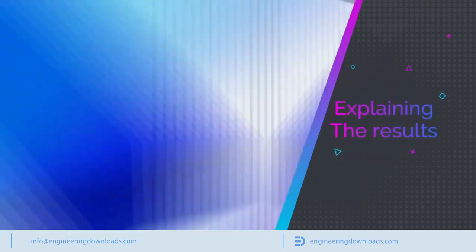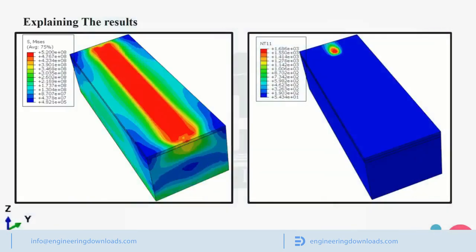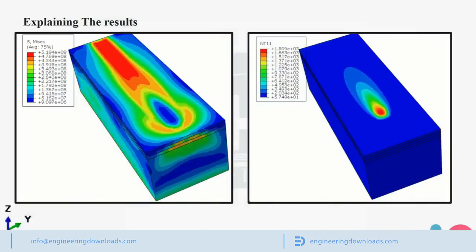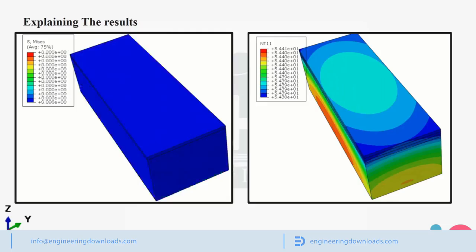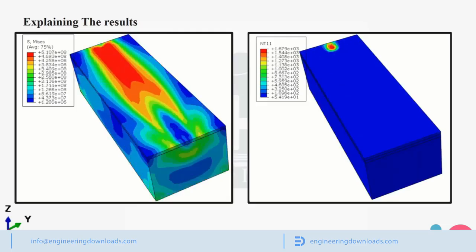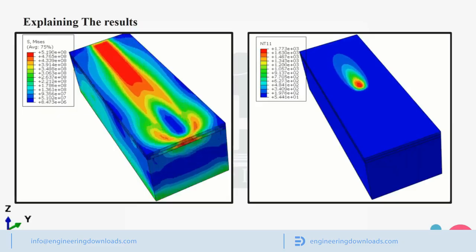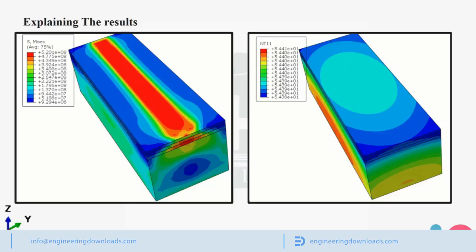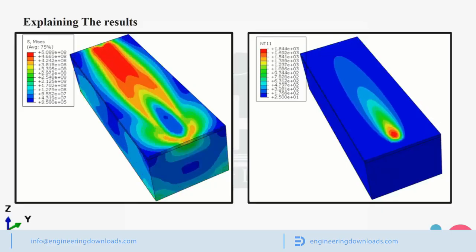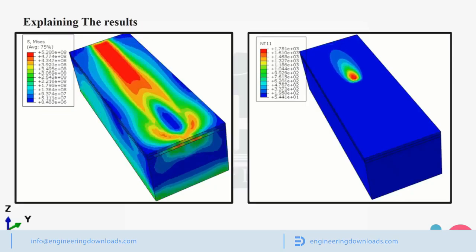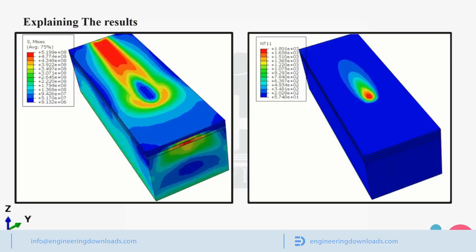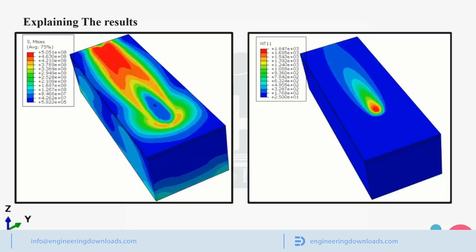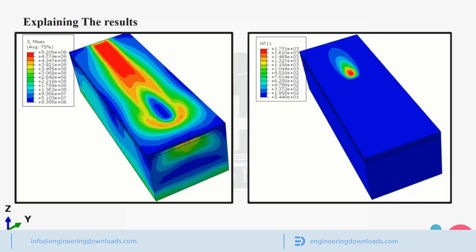As you can see in the picture on the right, first a small amount of powder is deposited on the substrate. Then the laser travels through the powder, turning it into molten liquid. Then the cooling process will be performed to turn the molten liquid into solid. After that, once again, the process is repeated. Some powder is applied to the layer. The laser travels through the powder and makes molten liquid. After cooling, the liquid turns solid. Another layer of powder is applied, and so on.